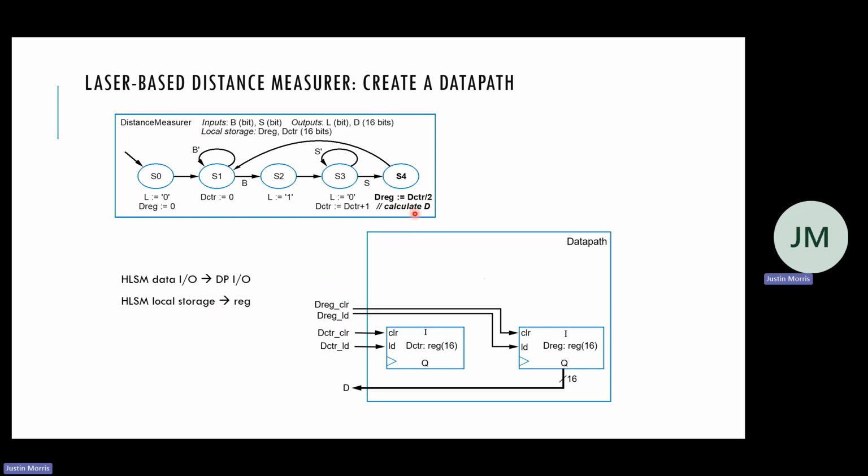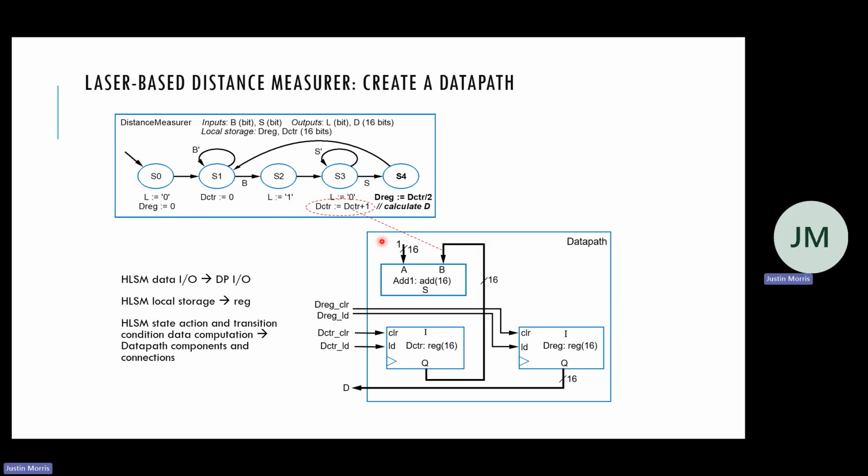And over here is when this one is enabled. That's our clears. There's our loads. Here's our adder. And the adder is connected to the counter, right? So we're going to add 1 when it's enabled. And then we need this shifter that shifts right by 1. It just takes the data counter, shifts it right by 1, and that is what gets saved into our output register. So this is my data path.